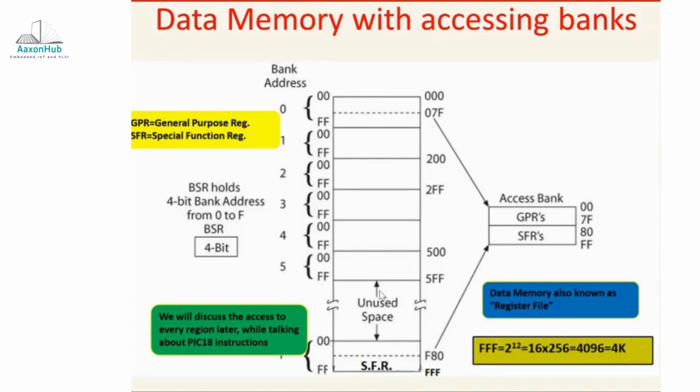Whenever you want to access banks, you need to check the general purpose register as well as the special function register. Until and unless an instruction is there, you need to understand what possible ways there are to read the data, and in that manner you have the access location for that particular BSR.